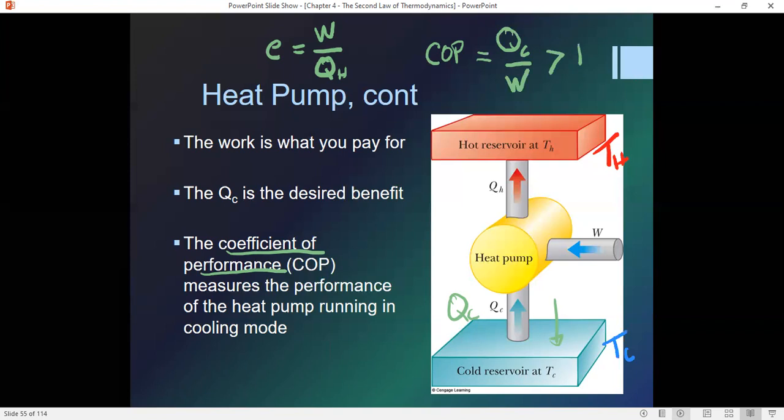With your air conditioner, you maybe want to cool your house down to 70. The outside temperature is 90. So there's a difference in temperature of 20 degrees Fahrenheit, not a whole lot. Your refrigerator is typically cooled down to 40 degrees, so there's a little drop in coefficient of performance there, and we're pumping the heat out to maybe 70 degrees in the house. The freezer is kept at 0 degrees. So again, that coefficient of performance is going to be less.